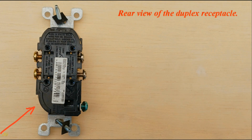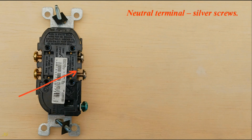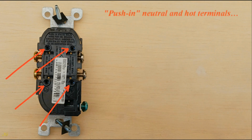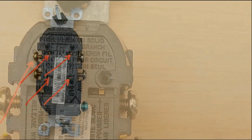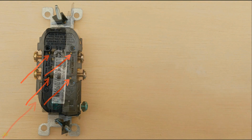Rear view of the duplex receptacle. Ground terminal, green screw. Neutral terminal, silver screws. Hot terminal, gold screws. Push-in neutral and hot terminals that accept only 14-gauge solid copper conductors in a 15 amps branch circuit as specified in the device description. Push to release tabs to remove inserted wire.